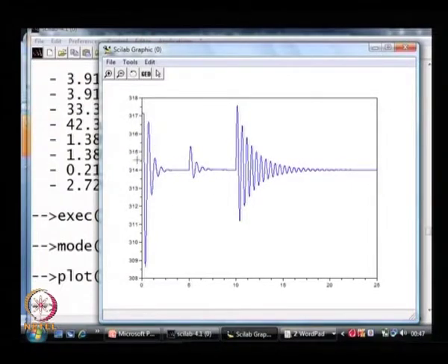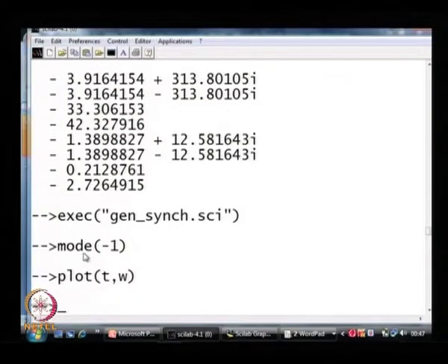So, the negative real part of the eigenvalue near Tm equal to 0 can be expected to be larger in magnitude than the real part near Tm equal to 1, where the magnitude is lower. This is actually true. So, this is basically a good correlation between eigen analysis and the simulation. This is what we see here.